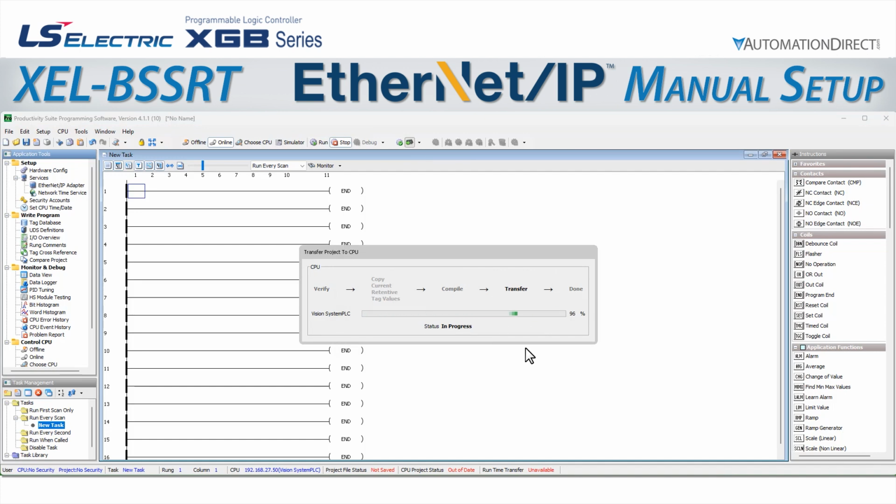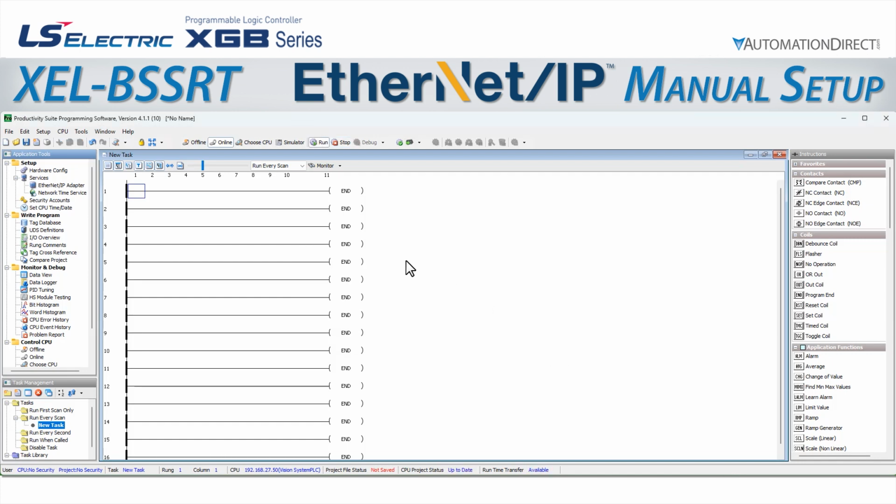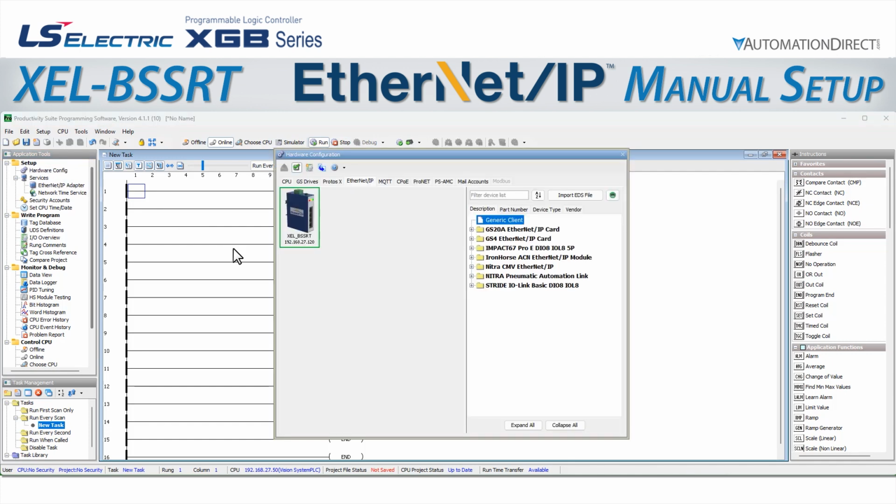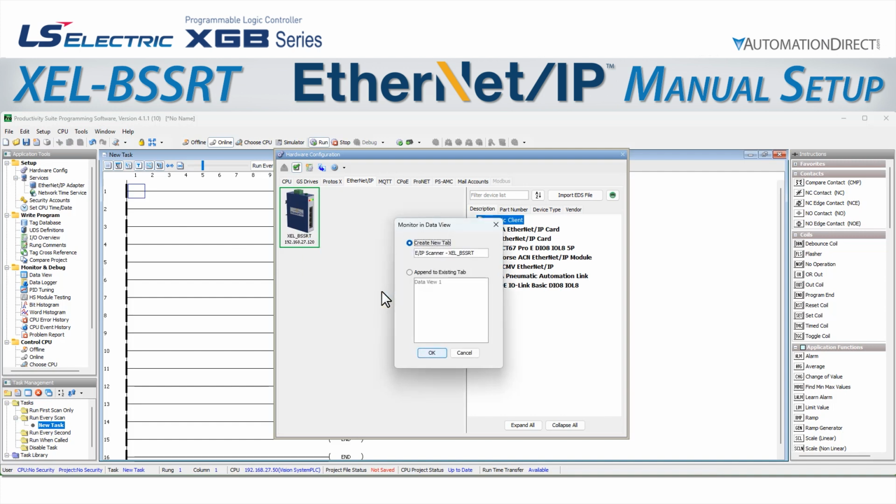and now let's create a data view window for the Ethernet IP information tags we created earlier. The productivity software makes this very easy because we can go back into our hardware config, right-click on the BSSRT, and select Monitor in Data View. The software then asks if we want to create a new data view or use an existing one. We will create a new one.